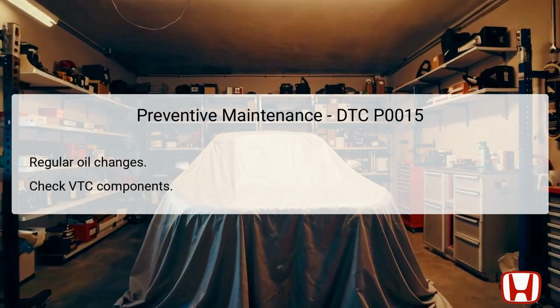Additionally, it's advisable to periodically inspect the VTC components during routine maintenance to catch any potential issues before they escalate. This should include checking for physical damage and electrical connectors to ensure proper connections. Following these preventive measures helps maintain optimal performance and prolongs the life of the engine.